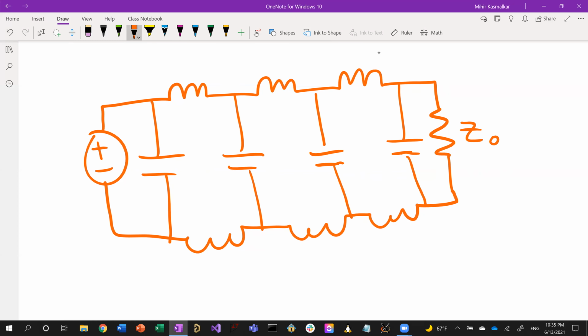And so what happens here? Well, you have your current propagating here, plus minus, charge building up, plus minus. That just continues happening, plus minus, plus minus. Then you reach the resistor, and from the voltage source perspective there's no difference between what it's been seeing so far and what it's seeing now. You'll see a voltage built up across here. You'll see a current flowing across the resistor. But for that same voltage, you'll still see that same current that's been flowing all this time through the transmission line, because the resistor has the same impedance as the characteristic impedance of the transmission line.